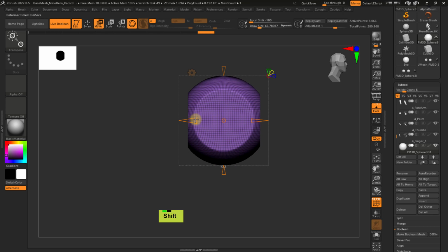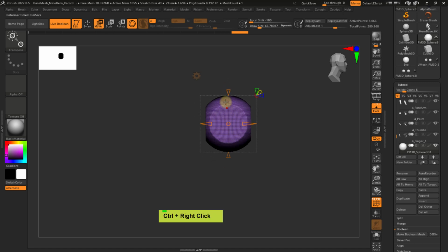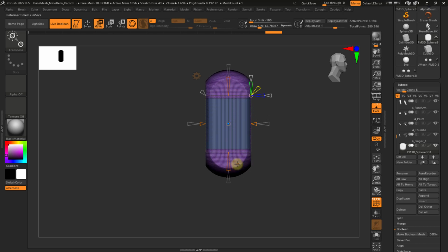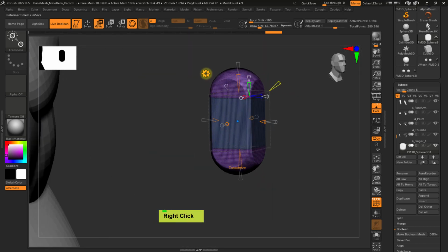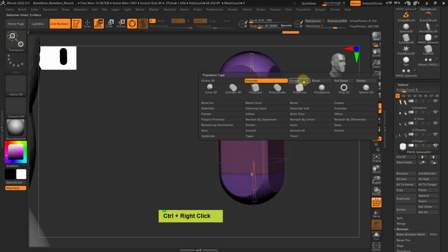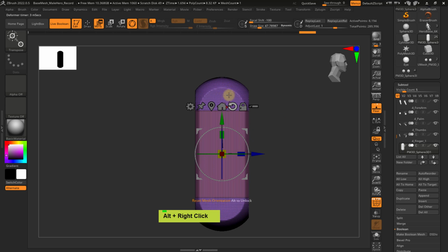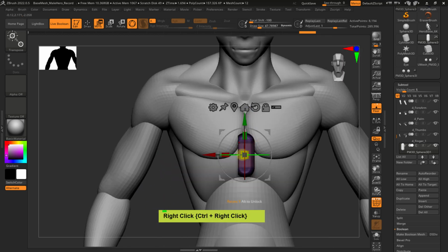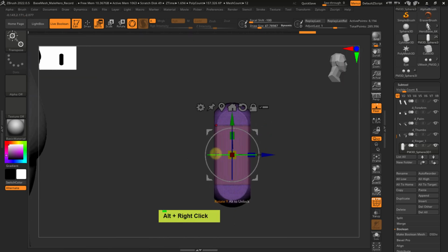So I'm holding the Shift key and looking for 0.2 and minus 0.2, which is great. And of course, we want to use Extract and pull this out. Which is, again, looking functional. Let me hit it, and maybe a little bit more. And there are no edges. I don't care about this right now, because instead of creating edges by using the segment cone, I will simply make it symmetrical and use the Remesh option. But how to make it symmetrical? It's not a left-to-right symmetry because I'm working in rotation. So I'm going to change this up.